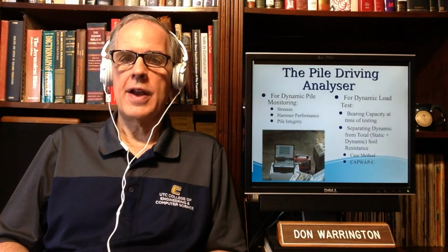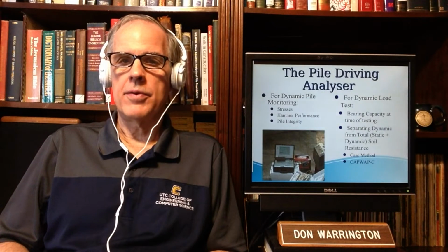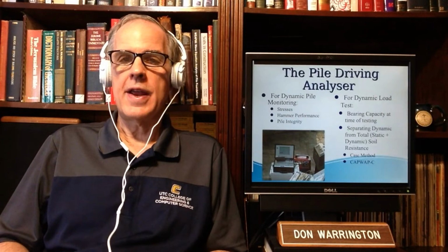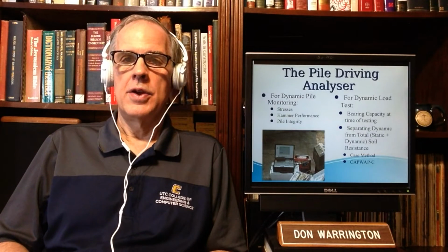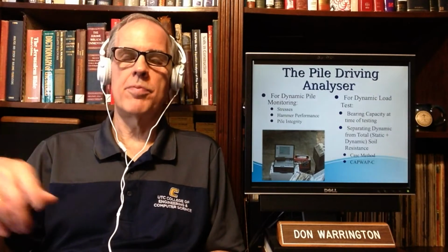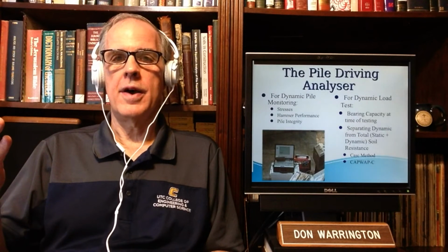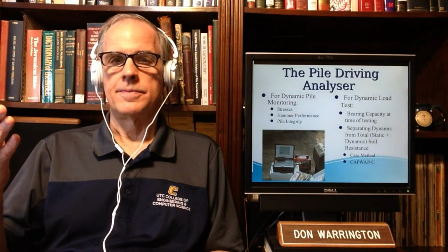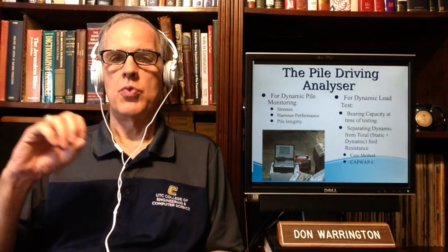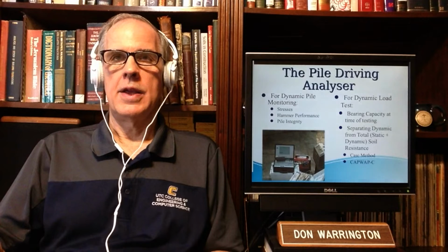But normally what we try to do with CAPWAP-C ultimately is we match up the data we get from the pile head, and we model the pile, and we try to eventually, through an iterative process, match up the data that we have with the response of the pile. In other words, we want to get to the point where the response of the pile matches the data that we're taking.